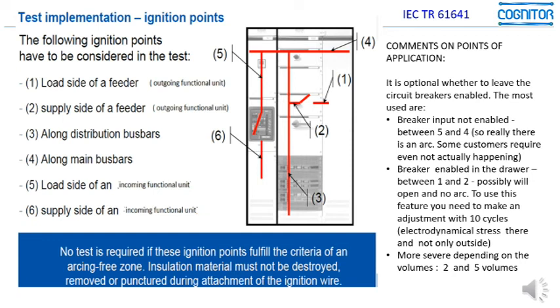Let's say when the user or the manufacturer is doing the test, he is able to ask the laboratory to do the tests with these ignition points. A very important point is that the manufacturer is not obliged to do all these points, if they are applicable. The manufacturer decides in which points he wants to do internal arc tests to register in the test report.